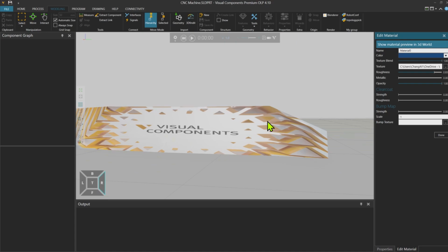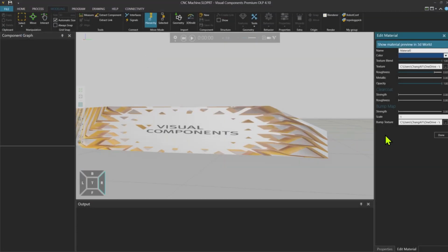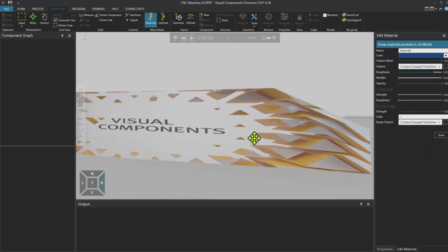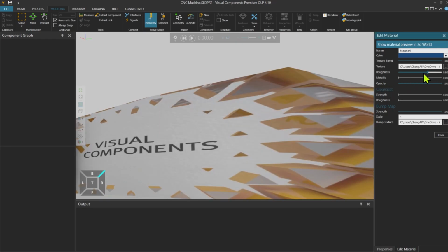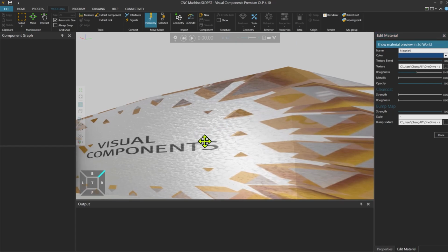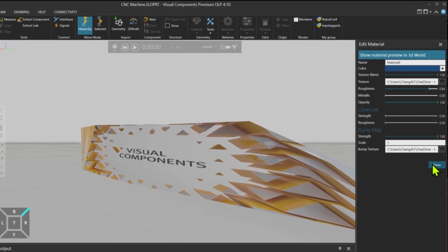So you typically find a blue texture for this. I can add the blue texture. And then if I increase the strength, you can see a little bit of roughness on this. So if I a little bit decrease the roughness, it's more and more visible, this illusion of surface detail. Let me just increase it to somewhere like 0.8. Okay, now that the material is ready, press done.